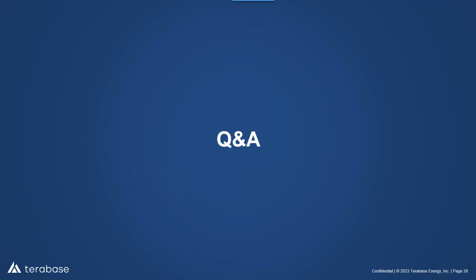Good question. So you can override the ASHRAE extreme annual mean minimum temperature as I showed in the demo, but the derivation of the delta T today for Solar Anywhere data is done through the research that Solar Anywhere has done comparing themselves to ASHRAE data. And one of the challenges of using other ground reference data is that it needs to be exactly co-located with the project site.